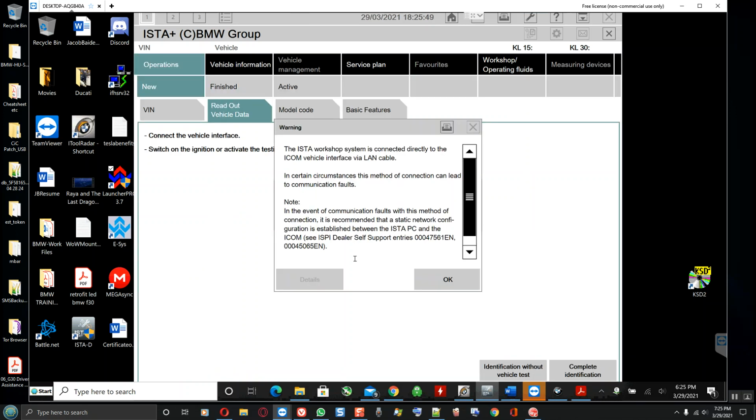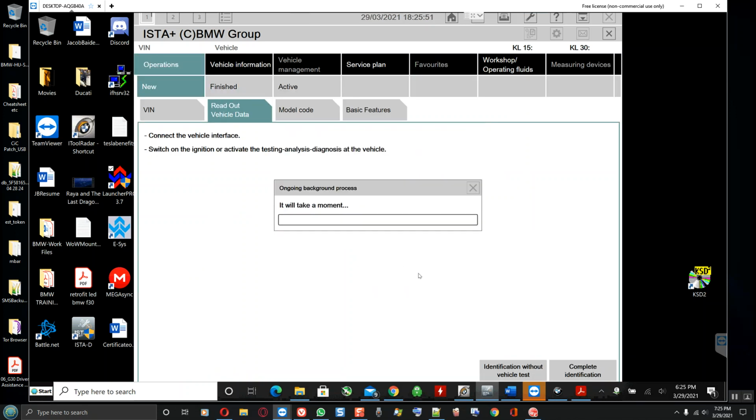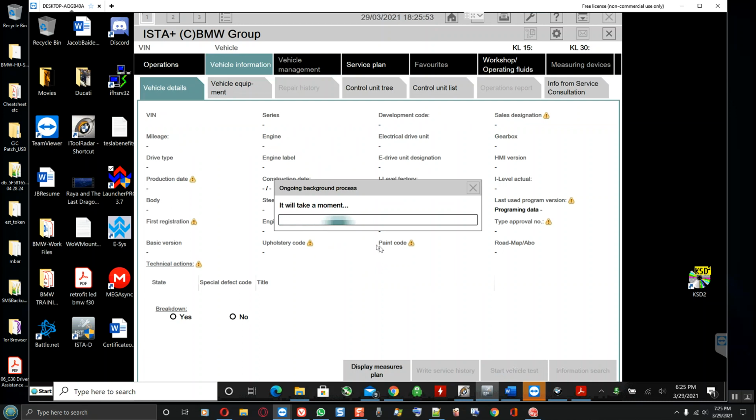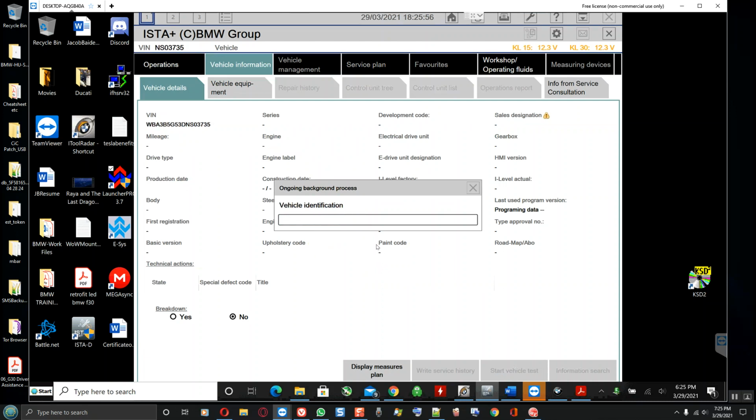No, you tried to do what? To do the unlock procedure afterward. Unlock the airbag? The airbag only unlocks when the car enters an accident. When you program a new airbag control module, you have to lock it with the service function in list D. We didn't put in a new airbag.